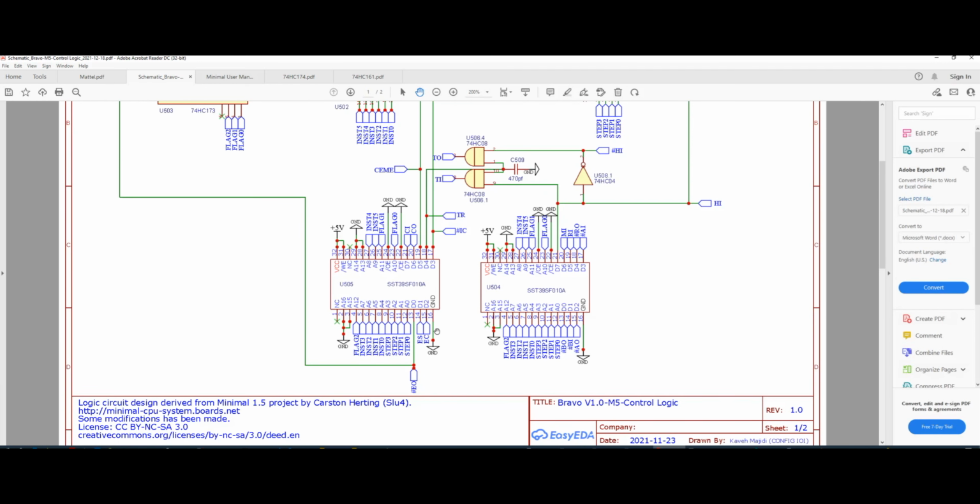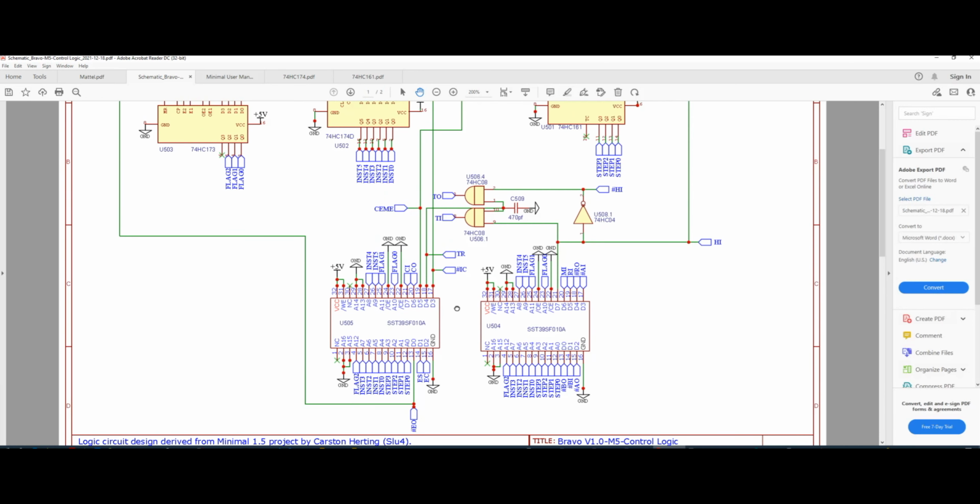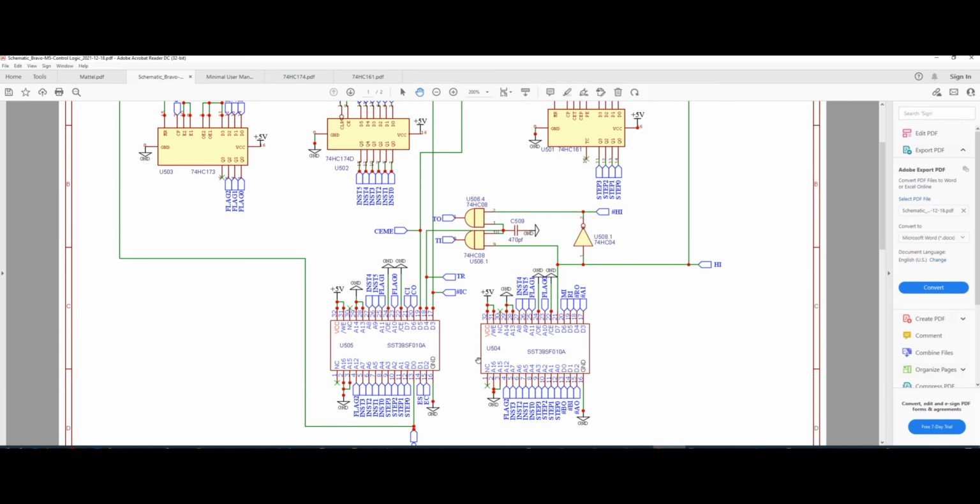Now, in regard to the signals that are outputting, if you look at the output lines, which are from D0 to D7 on each chip, you'll notice that each pin has been assigned a specific signal, and those are going to be our base signals. However, if you remember, we talked about how some of those signals are combined with each other to create new signals, right?